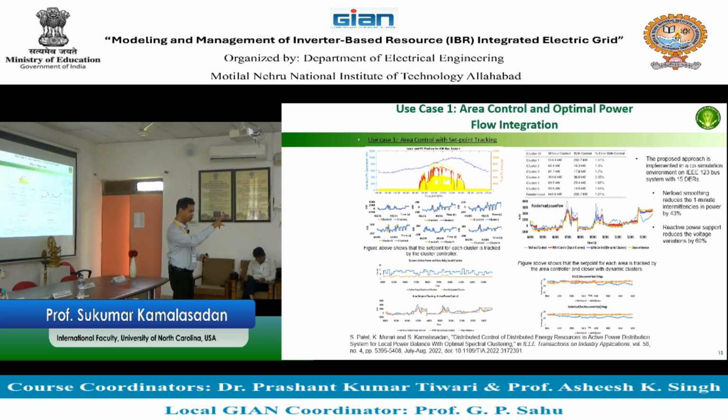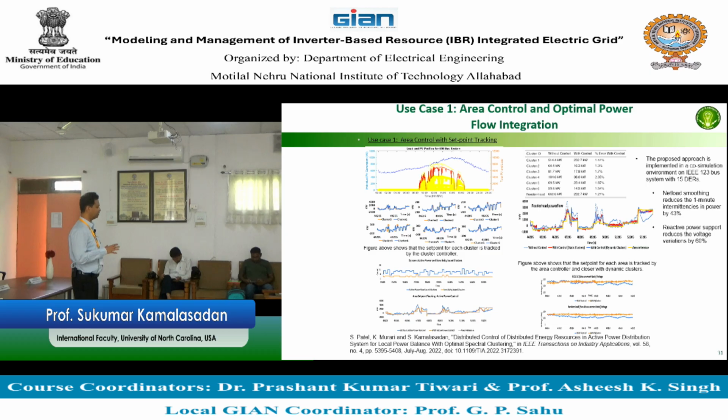Right? So the battery has two jobs. One job is to take care of PV, meaning when PV changes, the battery is absorbing this. Take care of that. And then in addition, the battery will give you this set point shape. Now that control is not easy. You have to look at the state of charge of the battery. You have to maximize the given capacity of the battery and do the two jobs.